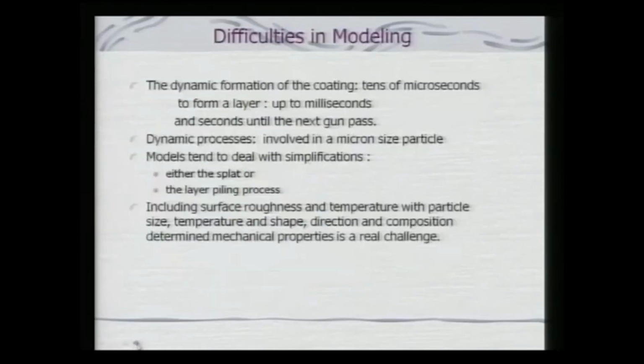Depending on the kind of gradients I provide, whether interfacial velocity or thermal gradient, I can interplay with the overall material properties to control the thinness of the splat and let it achieve a very high solidification rate. I can supply very high thermal gradients by enhancing the cooling rate and so on. So, I can control the overall structure by utilizing various material parameters as well as spraying parameters.